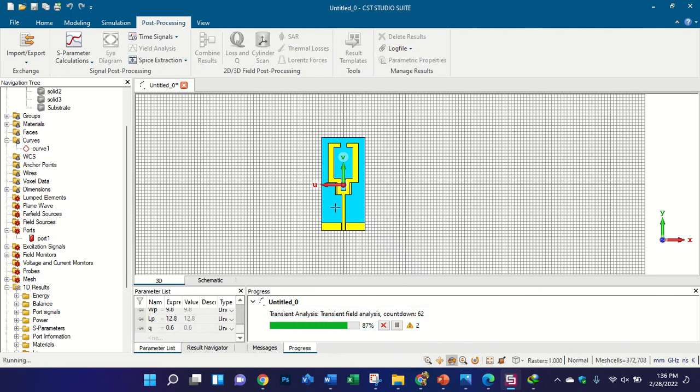And for the equations, you can add some equations, but not very complex ones, because this is not mathematics software. CST sometimes does not understand things like square roots and others, so you need to check these things. But for simple addition, multiplication, division, it understands. For complex mathematics, CST does not understand.